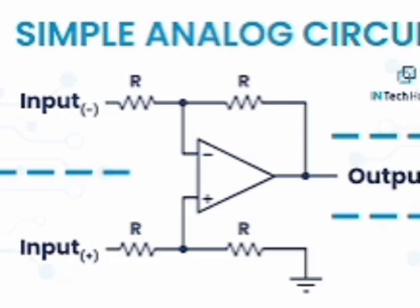BJT biasing in integrated circuits. Self bias circuits cannot be used to bias BJT in amplifier because R1 and R2 are large resistances and require greater area on silicon chip. Therefore, BJT is biased in IC amplifier using a special circuit known as current mirror. Basic current mirror: I out equals I in by 1 plus 2 by beta. Current mirror is symbolically shown as a constant current source.